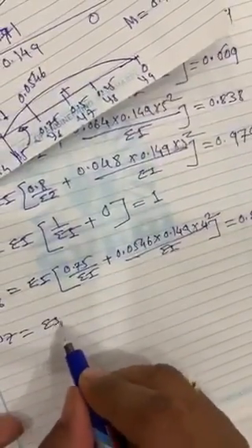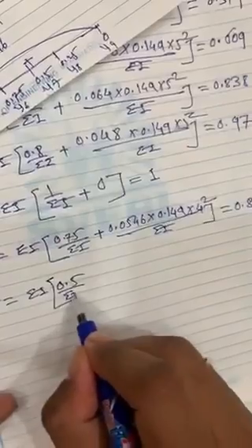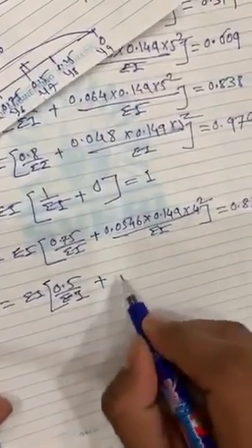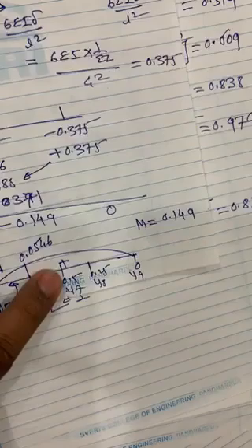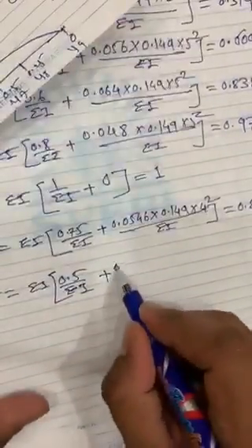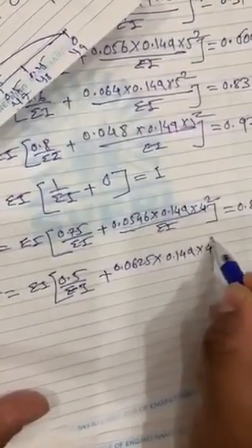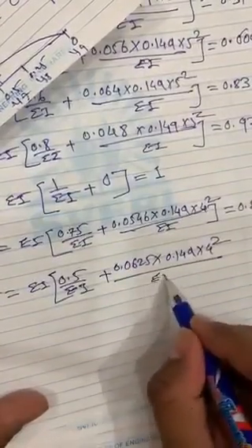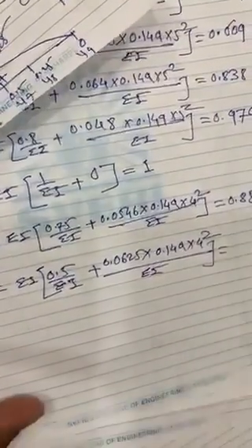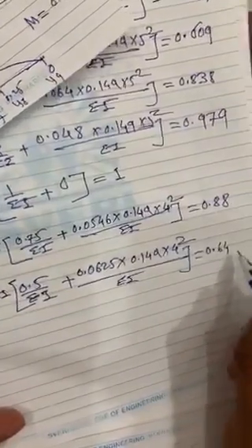Similarly we can get Y7. Y7 is EI in bracket, after 0.75 there will be 0.5 determinate value, so 0.5 by EI plus the k value for 0.5, which is 0.5 minus 0.5 cube by 6, that will be 0.0625. So k is 0.0625 into m, 0.149, into span 4 meter square divided by EI, and this value comes out to be 0.649.